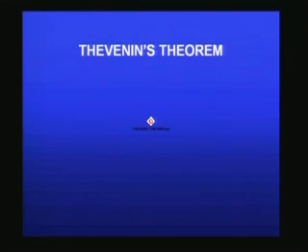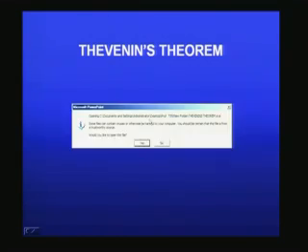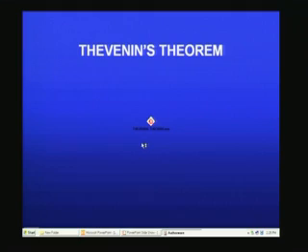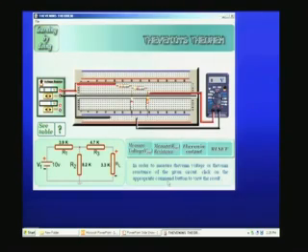Now let us try to simulate this whole measurement. I am going to show you on the screen a simple simulation of the experiment. You can see a breadboard coming over here, and the same circuit is put there. There is one 3.9 K, there is another 4.7 K which is R3, and the R2 is 8.2 K, and your load resistance is 3.3 K. That is connected to your voltage source on this side, and the output is connected to your multimeter on this side, and the circuit also for simplicity for reference is shown here at the bottom corner.